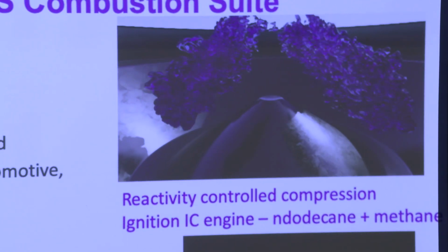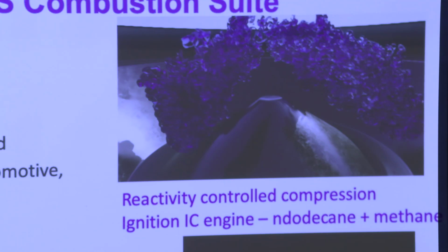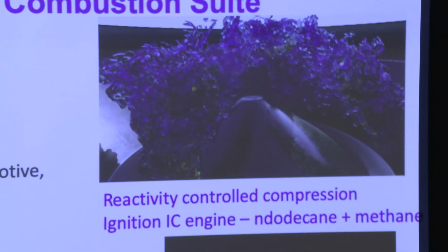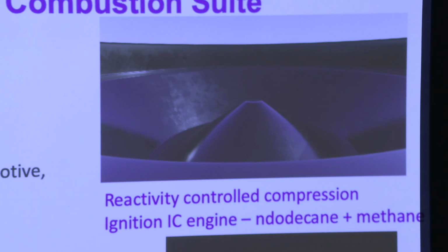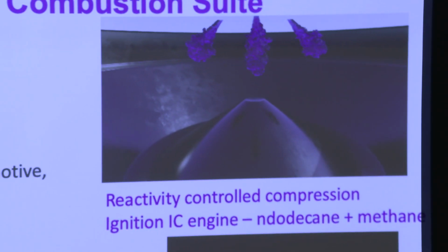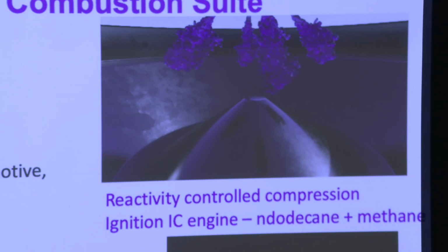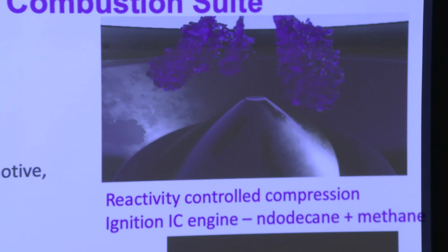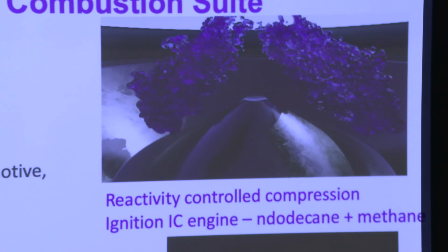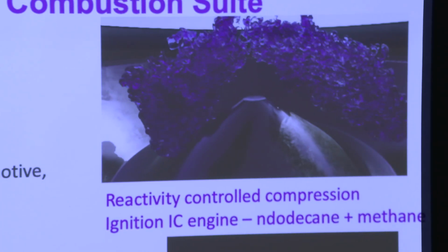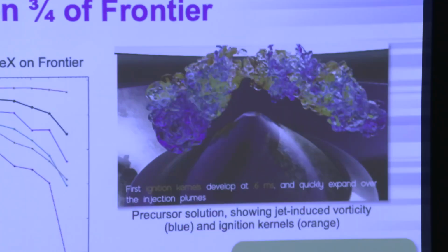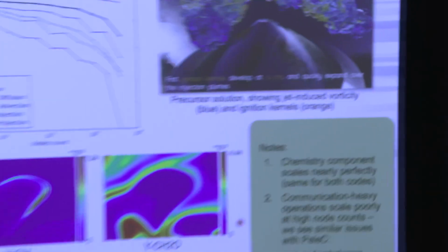And we were interested in watching the ignition process of the pilot, and then what intermediate species, cool flame species, were left when the main n-dodecane was injected subsequently. So we played around with things like the duration of the pilot injection, the time lag between the primary and pilot injection, and then the mixing and ignition phenomenon.